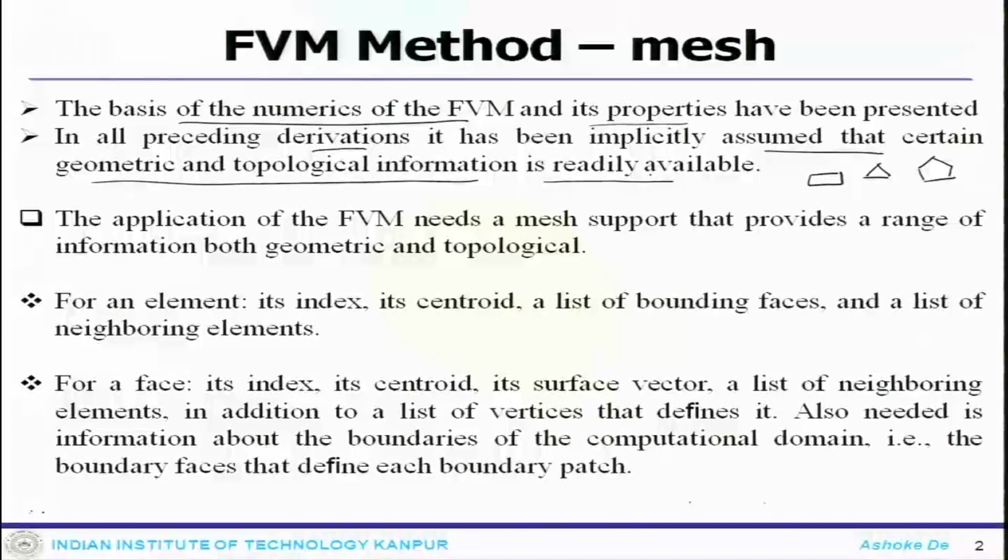Now, what it essentially means is that whenever you do a calculation, you have a physical problem in your hand. So, that is your physical problem, along with your geometrical information or modeling, and the governing equation that will define the physical problem. Then the physical domain is converted to the computational domain, which you call a mesh or grid, and then you discretize the system and get a linear system to get a solution.